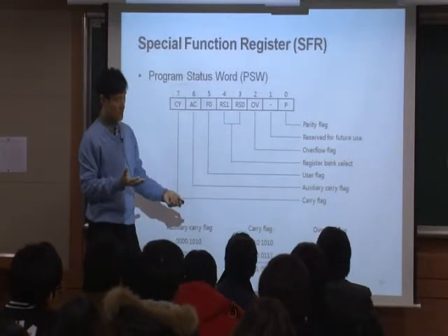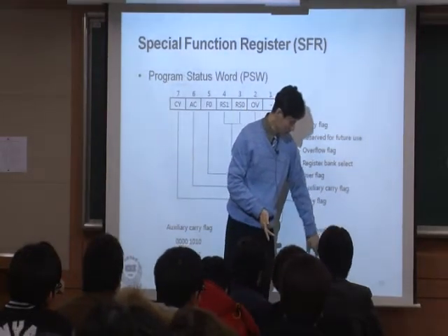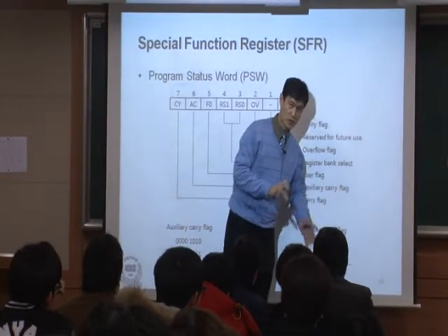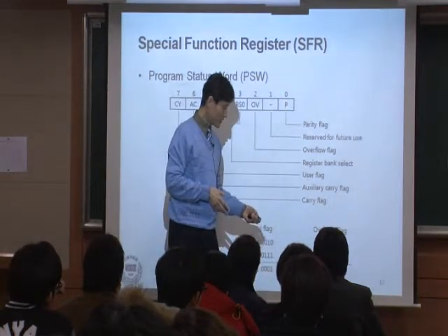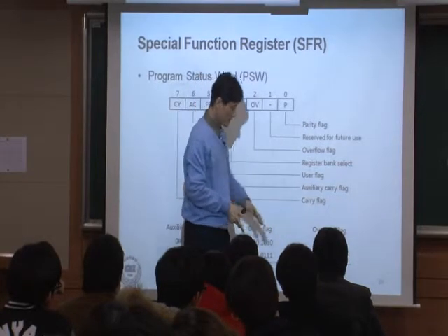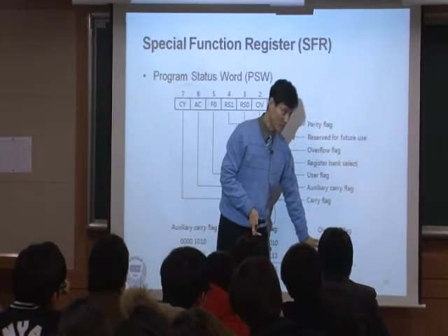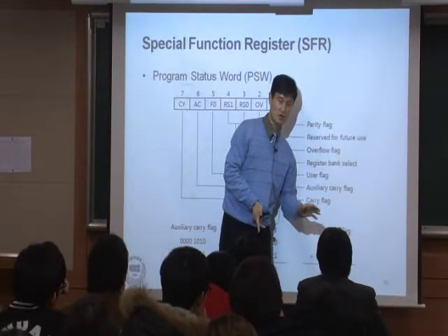Think about overflow now. In this case, 8 bits plus 8 bits is again 8 bits. No problem, right? However, look at the first bit, called the MSB, most significant bit. Both of them were 0, but now the output becomes 1. That's the condition of overflow.